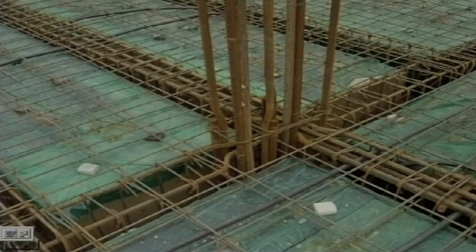already I have shown, but let us come here specifically: this is your beam reinforcement. You see, this is the slab, the reinforcement, and you are providing this one. Please note all these things are provided here to give clear cover, because otherwise it will just simply lie on the floor of the formwork. So, you will not get the clear cover. So, you have to provide that clear cover here, here, like that in different places you have to give that clear cover.